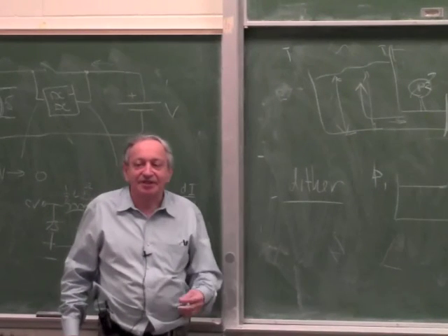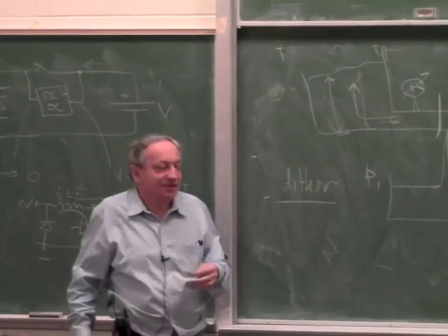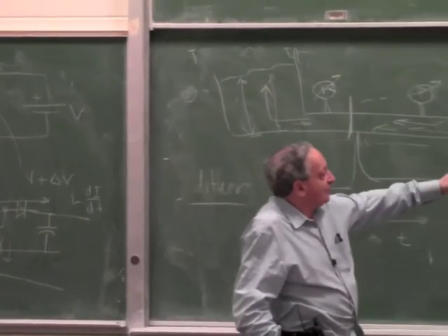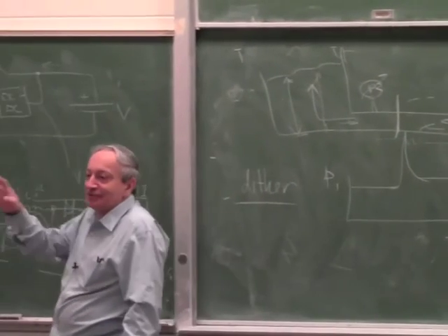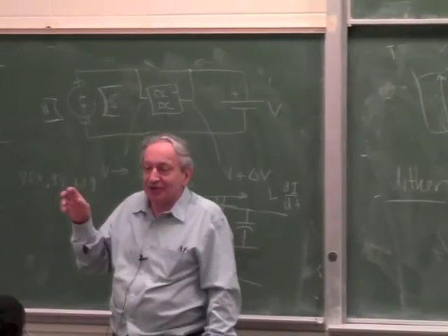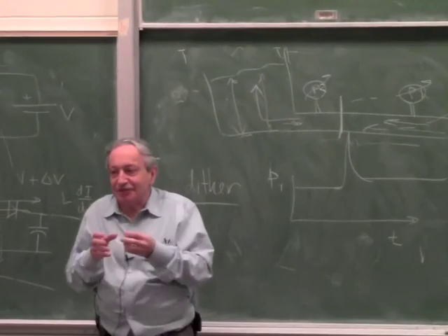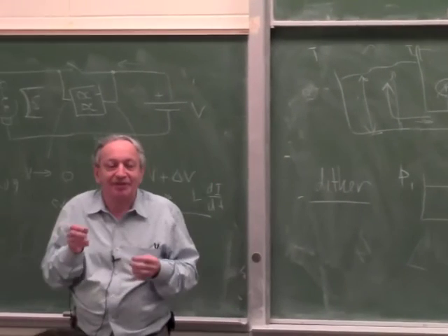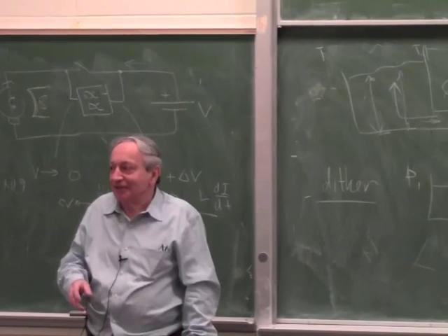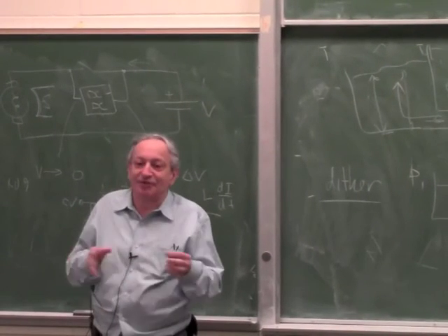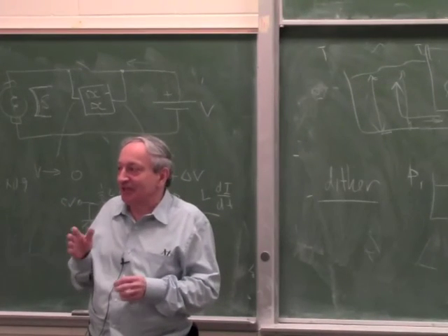See, hydraulic servos have a lot more stiction than electrical things. Because the nice thing in electrical servos, the electrons can flow very smoothly. Whenever you start the smallest current, or smallest voltage, the electrons start flowing. But in a hydraulic system, when you have valves and pistons, there is static friction. You increase the pressure a little bit, it doesn't move. Just like stiction in mechanical systems. Right? You have to overcome static friction before things start moving, and that causes some backlash in a servo. A bit like hysteresis, right?